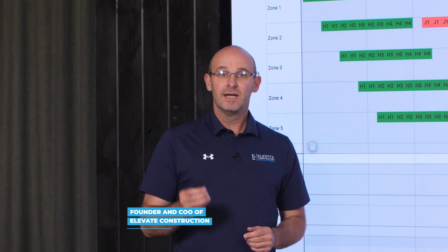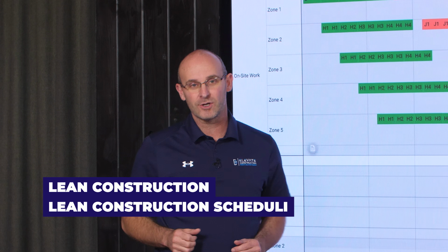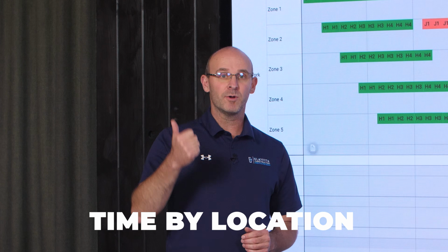Okay, so I am super excited about this topic because Takt Planning is the foundation of everything we should do in lean construction and in lean construction scheduling. It's in a time by location format. Typically, the industry has told us that it needs to be in a time by deliverable format, and that is incorrect. We need it in a time by location format because we want to see, and this is the big word, motion. Motion. We want to see how trades flow through the project site.